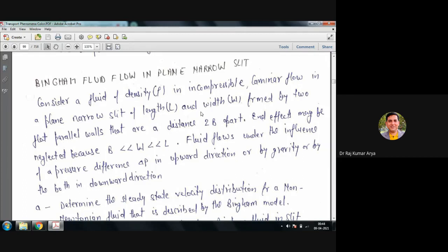So, the Bingham fluids, you cannot make them flow on a single plane or surface. The idea behind that, actually, is that the weight of the fluid itself may not be sufficient to provide the driving force which can go beyond the critical force required to make them flow, right? So therefore, you need a confined space where you can apply sufficient force to make it flow.